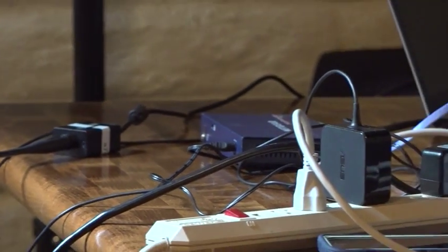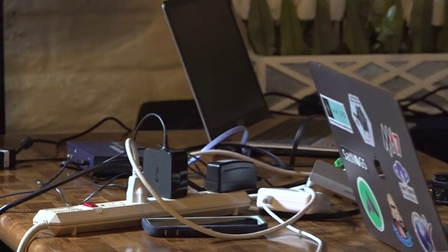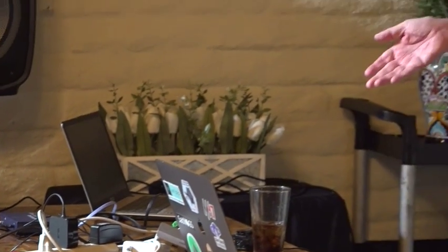So this is actually overkill if you just want one signal at a time, like on HF. You're grabbing and processing all that data only to throw most of it away and look at a very small piece of it. This thing really comes into its own when you want to receive lots of channels over the whole band at the same time.